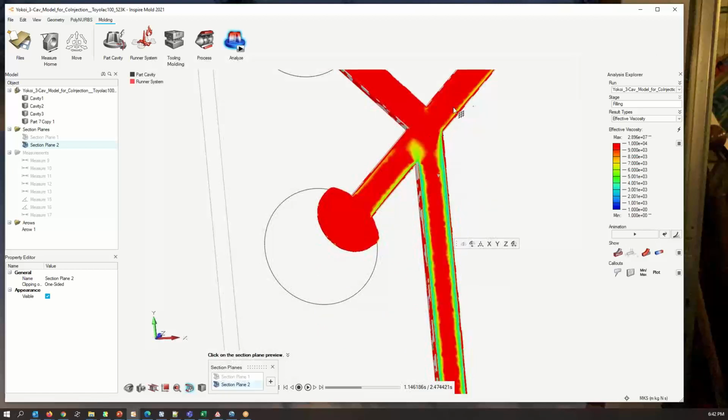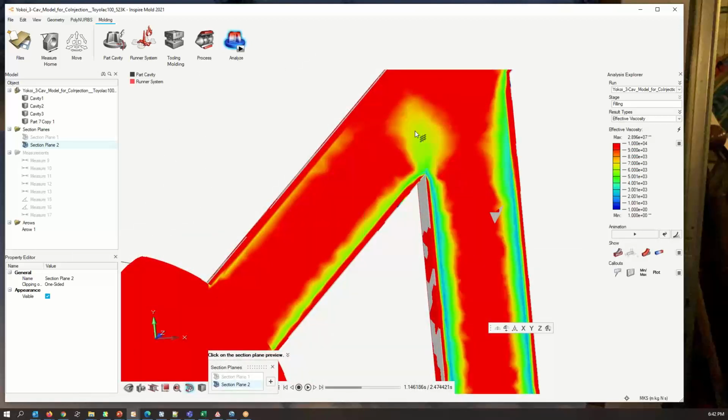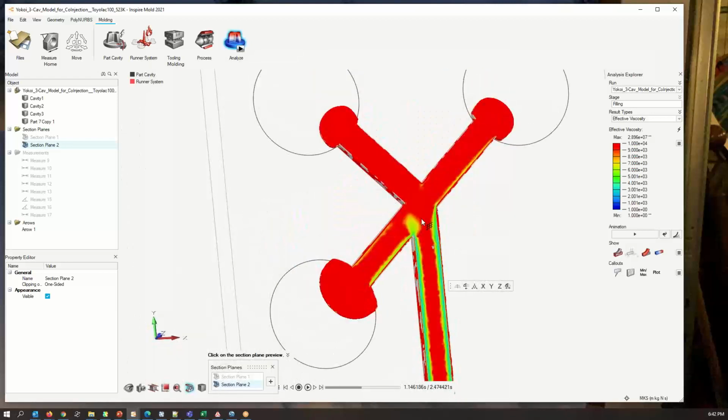And a little bit might track along here as it goes, but right in here, I see lots of it. And in fact, this is shear thinning a whole bunch. This viscosity is dropping tremendously in here. I'm going down to 1 Pascal second coming in along here. I've got 4,000 Pascal seconds versus 10,000 plus out here. And so it's going to draw more flow on this, even to this side of the plaque. It will draw a little more flow coming through here. So this shear thinning effect, looking at what happens to our viscosity.